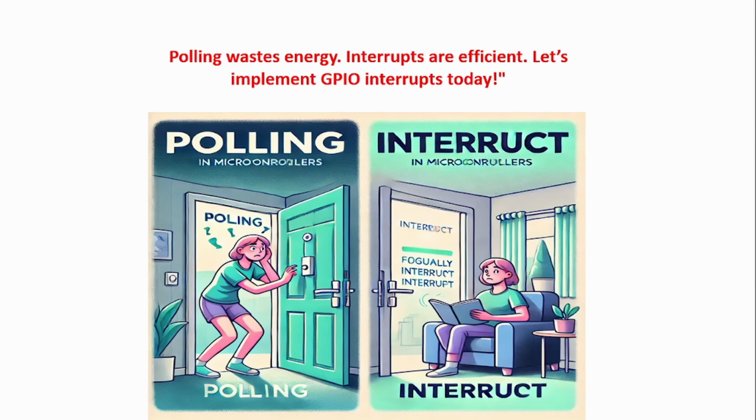So till now, whatever we have developed based on GPIO, ADC, I2C, they all are based on polling mode. Polling mode means we are continuously waiting for some event. If you follow the previous videos, you must know that we wrote if LED is equal to 1, or if UART is equal to 1, or if ADC is equal to 1, then execute this. So in the program itself, we write one loop, like if X is equal to 1, then execute this. This is called polling mode.